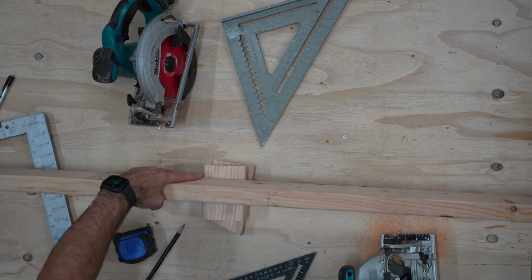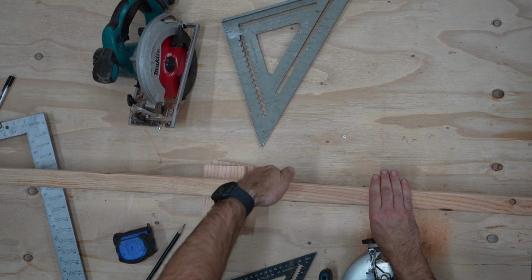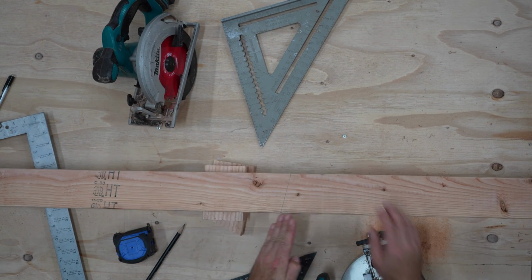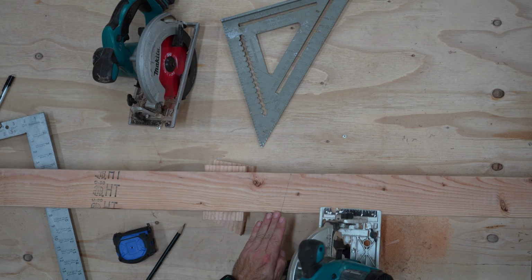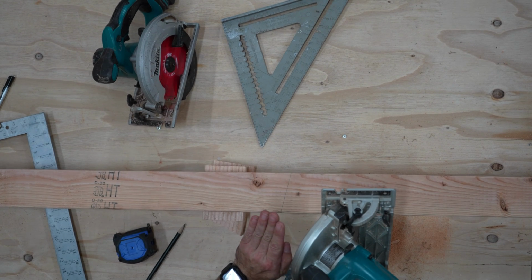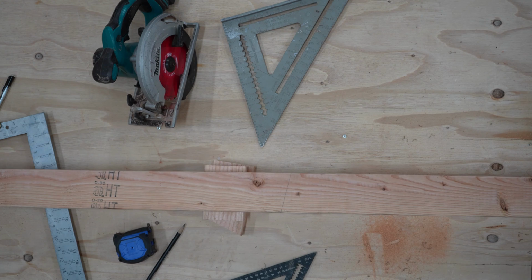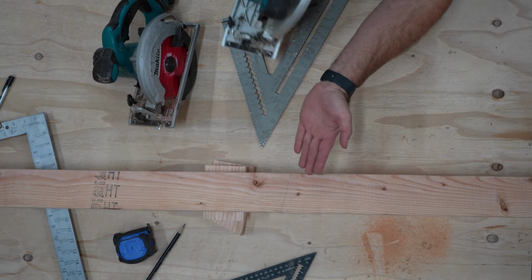Here is how I like to double check the blade is going at the correct angle. I hold my hand at the angle the line needs to be cut. Then I check to make sure my blade is leaning the same way. Here it was not, so I moved to the other side, and now my hand and the blade are leaning in the same direction.